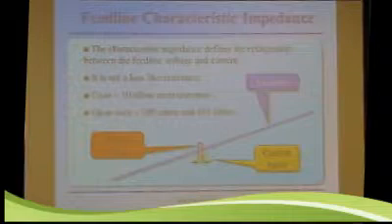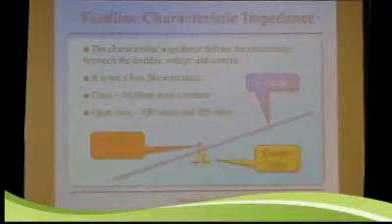Coax is typically 50 ohms. The cable companies use 75 ohm coax, but 99% of ham operators use 50 ohms. Open wire is usually either 300 ohms or 450 ohms impedance, and it has to do with the characteristic impedance of your antenna. Or at least its importance has to do with the characteristics.